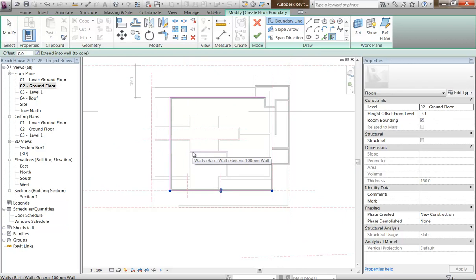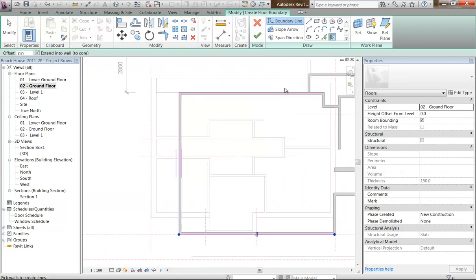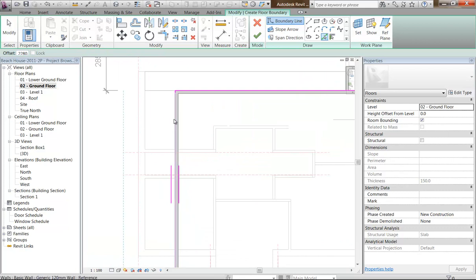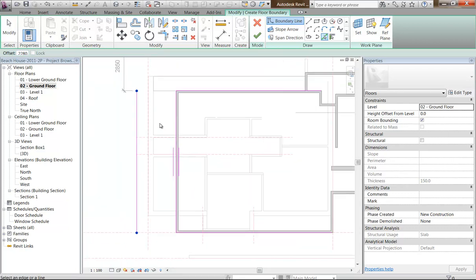Okay, now I just want to check one measurement here. So, okay, so that floor, I didn't put this measurement on the drawing for you, sorry, but I just left that off. So 2280. Okay, so we're going to use pick lines here and put offset in on the options bar, 2280. Again, I just took these measurements from the drawings that you'll be given probably today. Okay, so it does cantilever out a little bit.